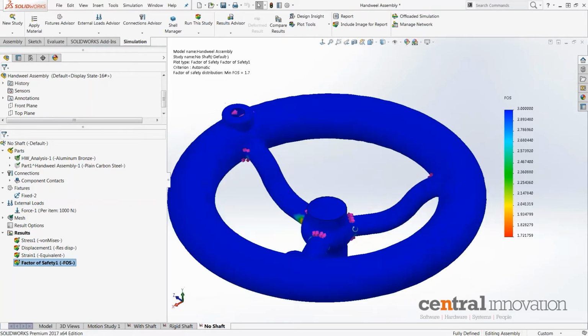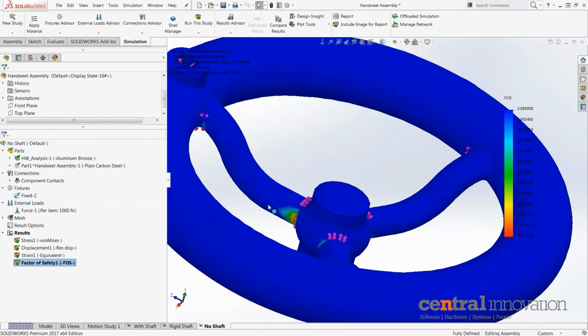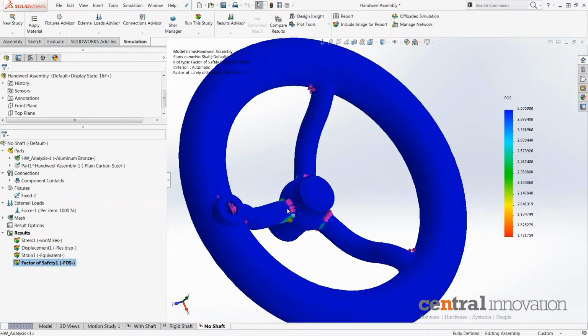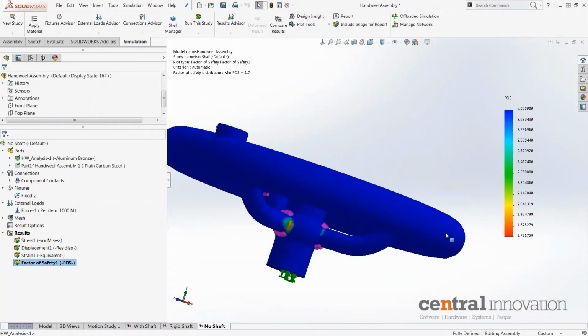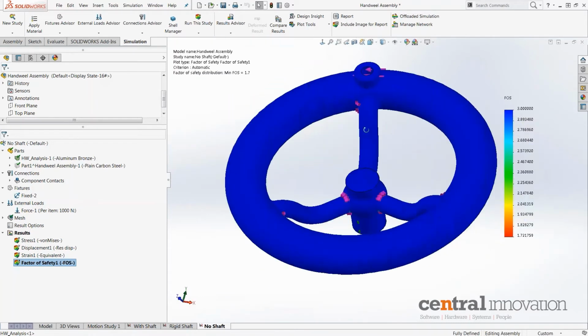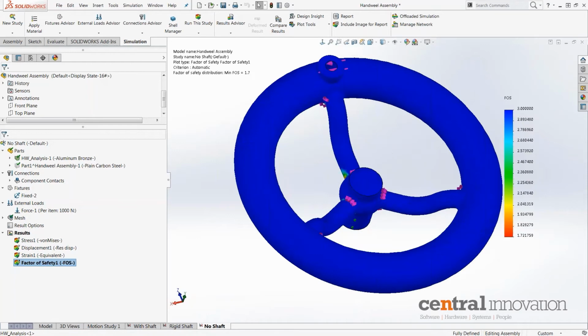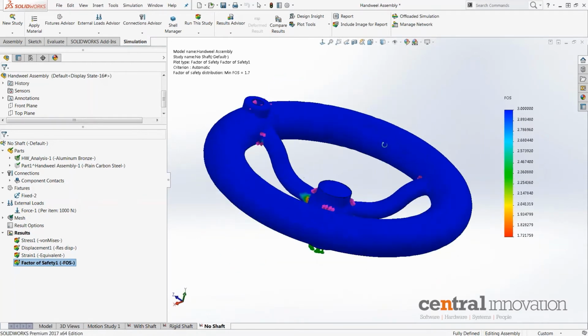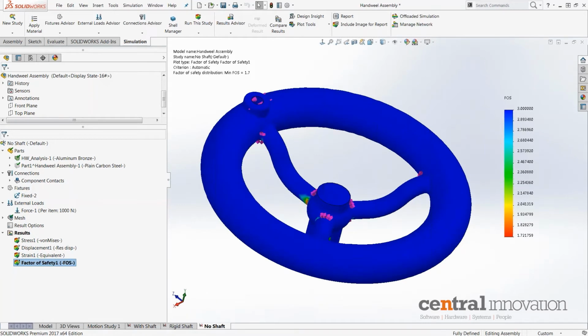And this is done by no other major changes except for the meshing. So I used mesh control in order to focus my calculation on these areas and therefore achieve a much better, much more accurate result. In this case, 16% difference. For some, that might be an acceptable error, and it generally is if you're only trying to see where the weak points of the design are.